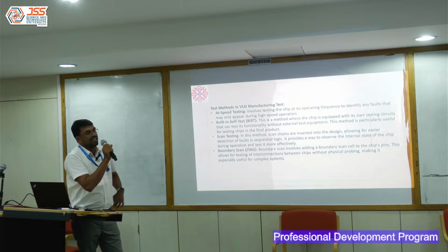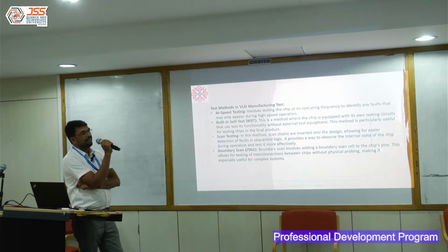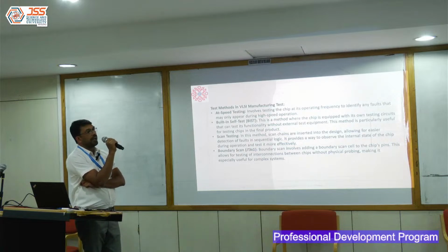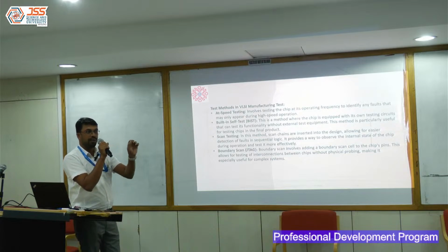No, whatever you do, that is fixed. What I'm saying is, setup you can work around by delaying the clock. Setup is the minimum amount of time the data has to be stable before the appearance of clock.